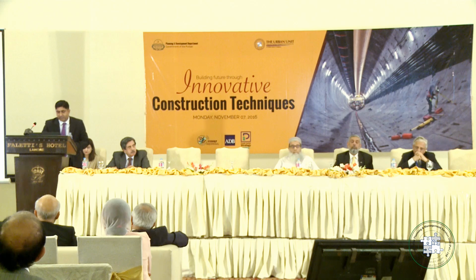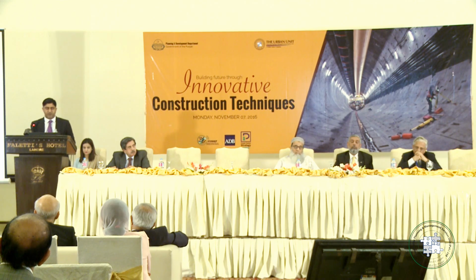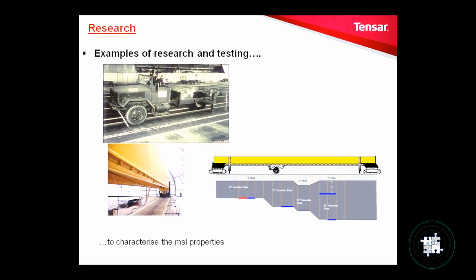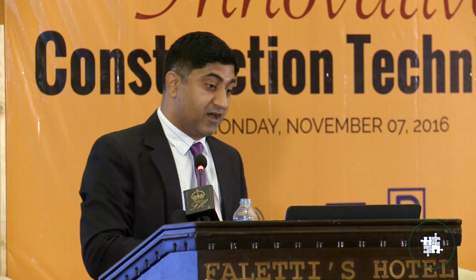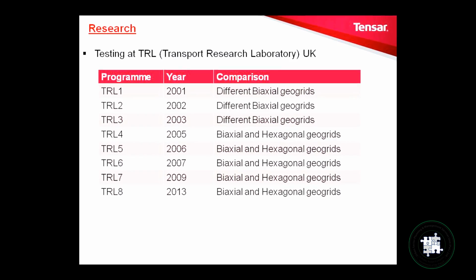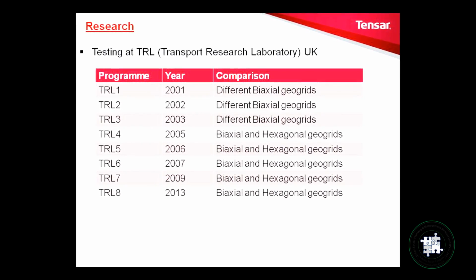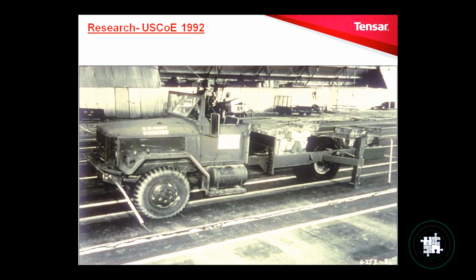Then TRL testing, I would say this is one of the biggest research works carried out in the world. TRL 1 started in 2001, and eventually TRL 8, we finished this kind of testing in 2013. We monitored different grids, biaxial, hexagonal geogrid, and we can see the performance. I'll quickly go through only the US Corps of Engineers research work from 1992, 2000, and the recent research work.